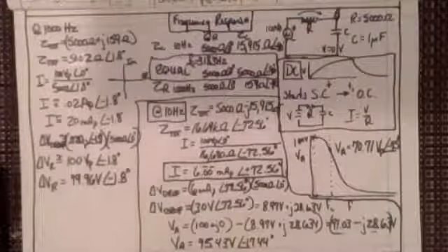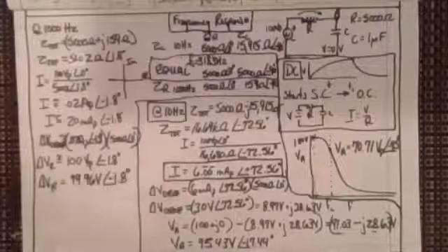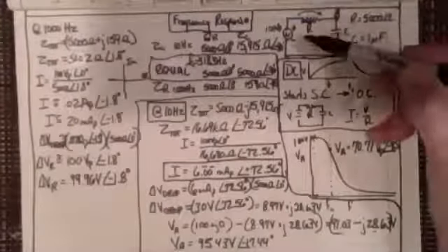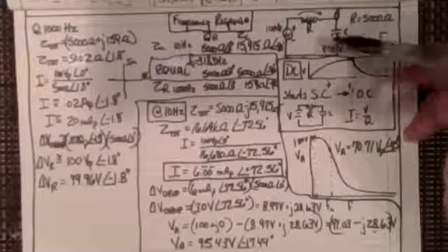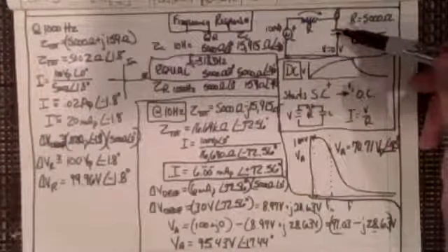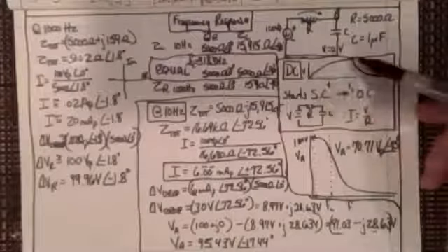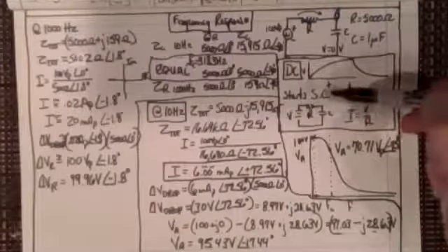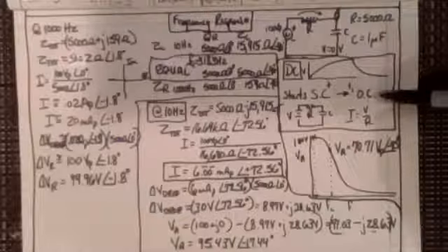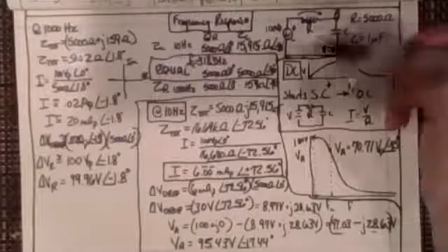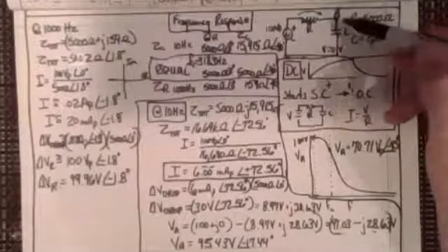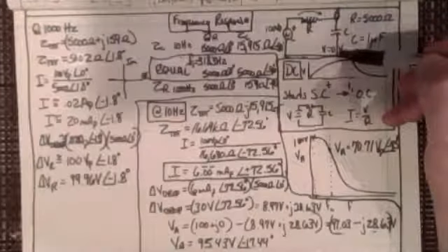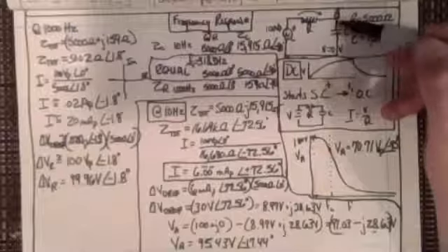Now, how do we understand that conceptually? When we look at the circuit that we have here, we can see that as I'm closer and closer to DC, I'm closer and closer to that thing where this starts as a short circuit and ends as an open circuit, right? I don't want you to understand it this way, but I'm just sort of telling you. So as we get over there, this is holding off at lower frequencies.